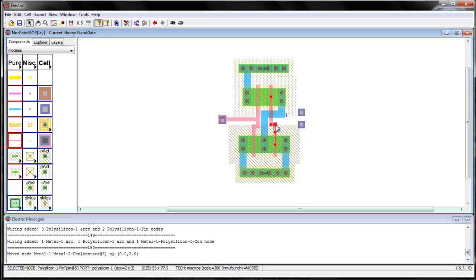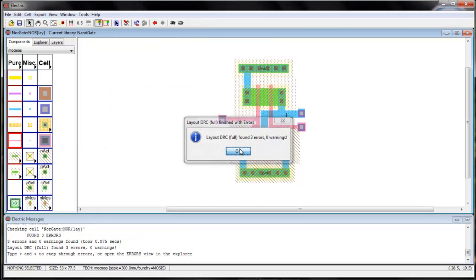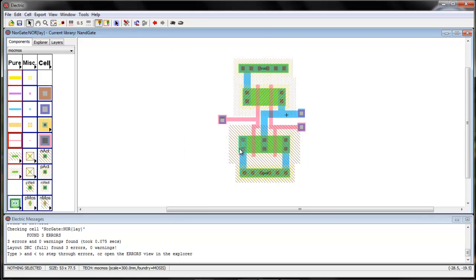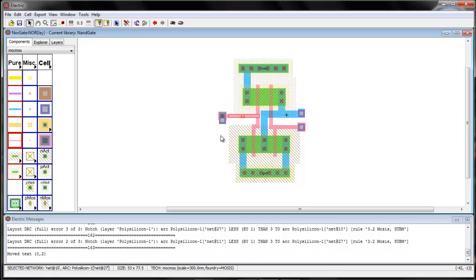So you can just left click, right click in between, right click again, left click, right click. For metal nodes it won't show a problem, but metal contacts. But when you are connecting two different layers, yes, it might show some errors. Make sure that you're checking for DRC errors every now and then, so that they don't pile up at the end, and you can sort them easily.